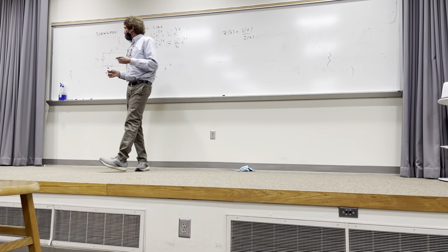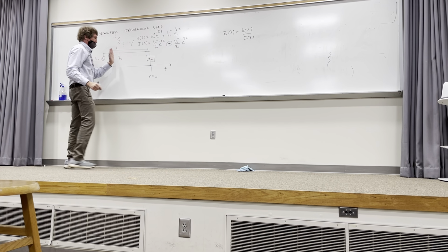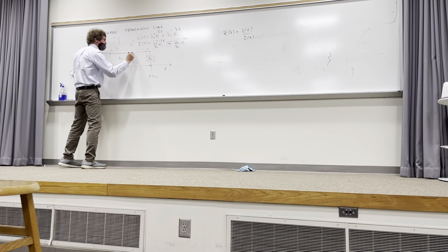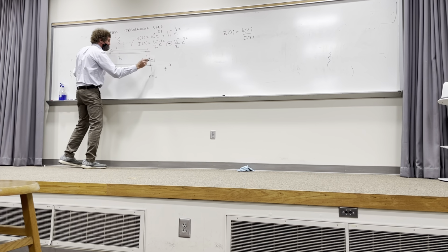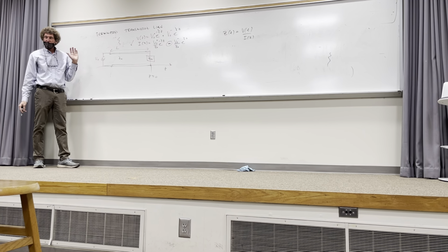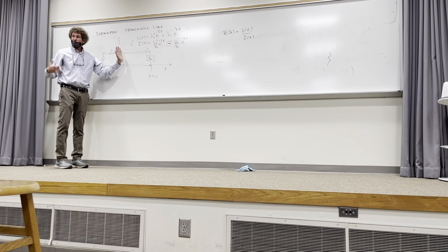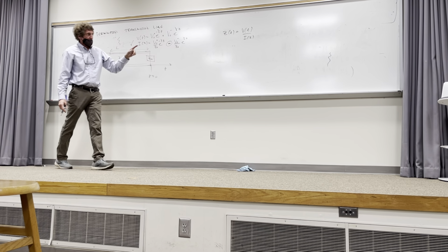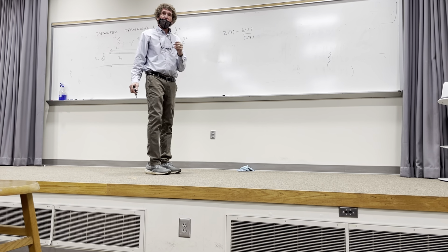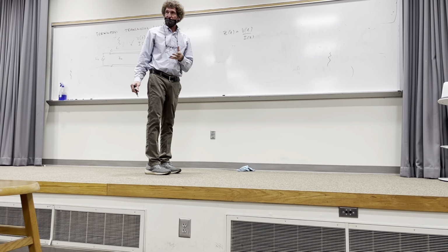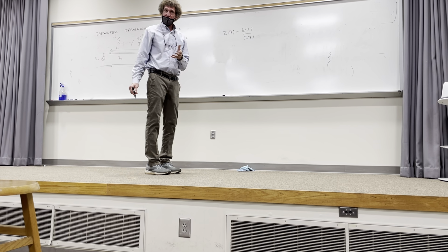All we're doing is saying if we're at a given point Z in the line, anywhere, and I didn't show the twin conductors here, but y'all follow me, I'm just trying to show you it's a transmission line. If you're at any point Z, you have a current that's measurable and a voltage difference that is measurable. The ratio of the voltage to the current at that point is called an impedance. It's given by this ratio, and that should be apparent to everybody. You know what impedance is, right? You've done a lot of stuff in there.